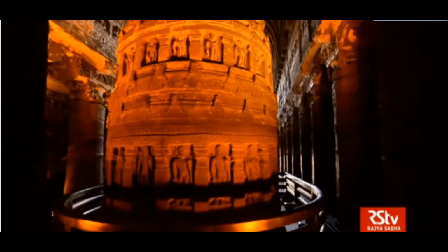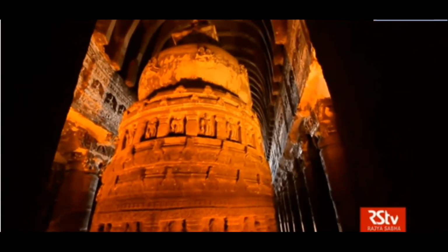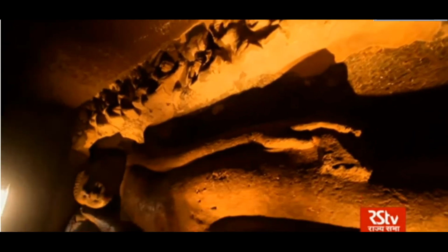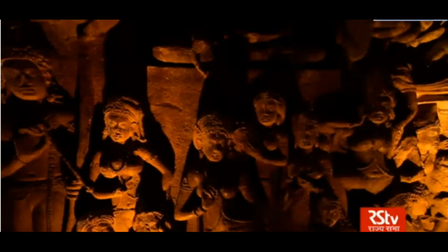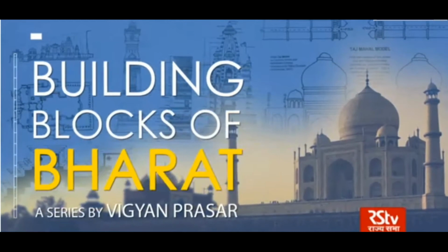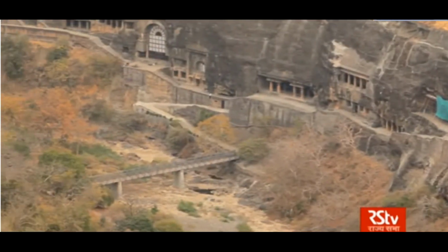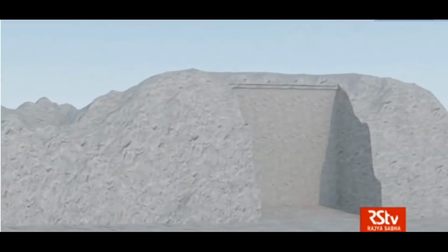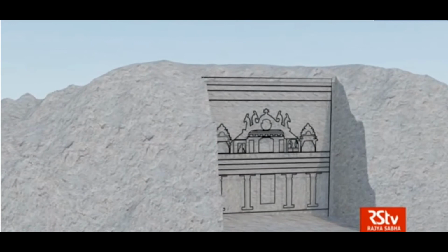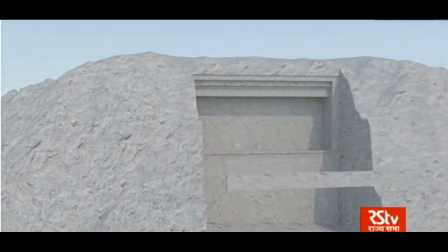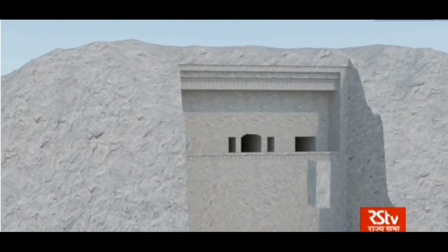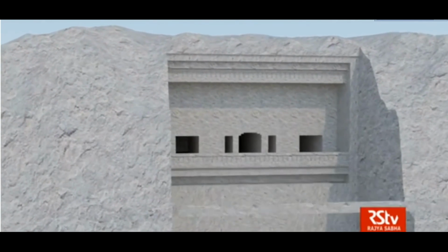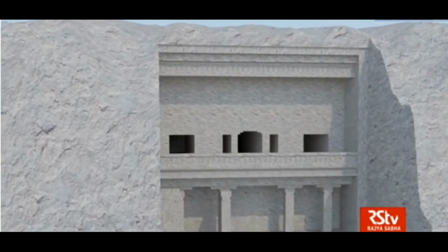A notable trait of this kind of rock-cut architecture is the crafting of rock to imitate timbered and carved wood. It's used here. First off, the outline must have been marked. Then excavation started from the ceiling, which was finished first. The work then continued downwards till the floor was reached.